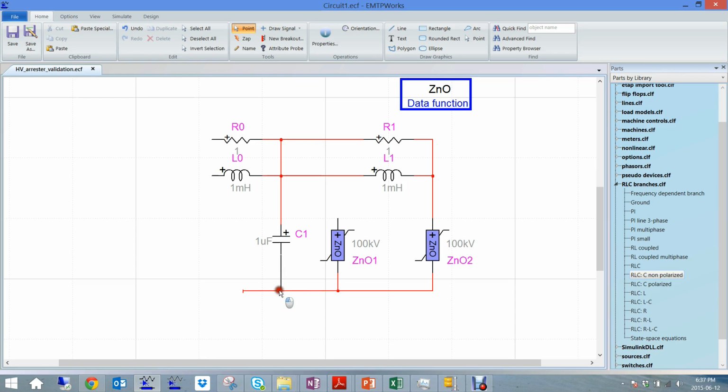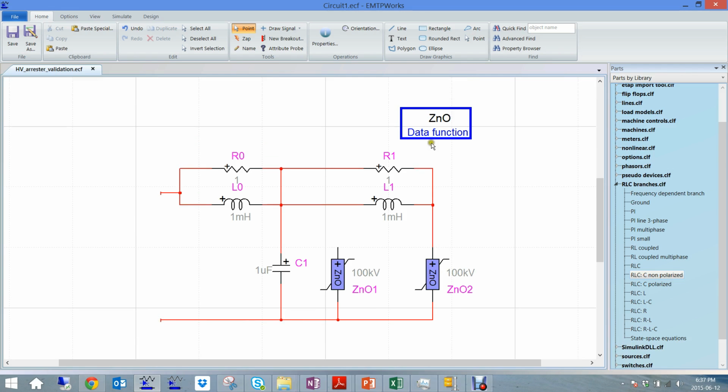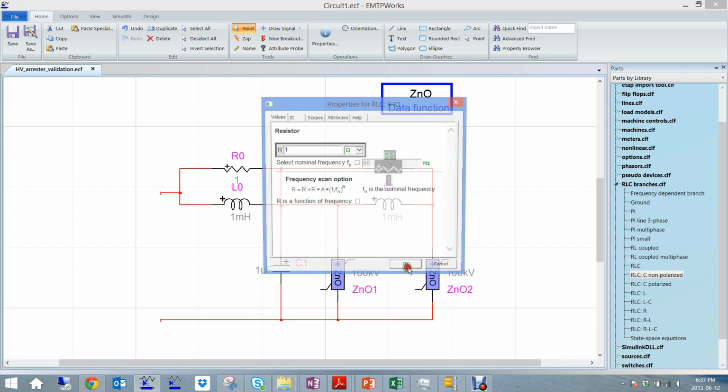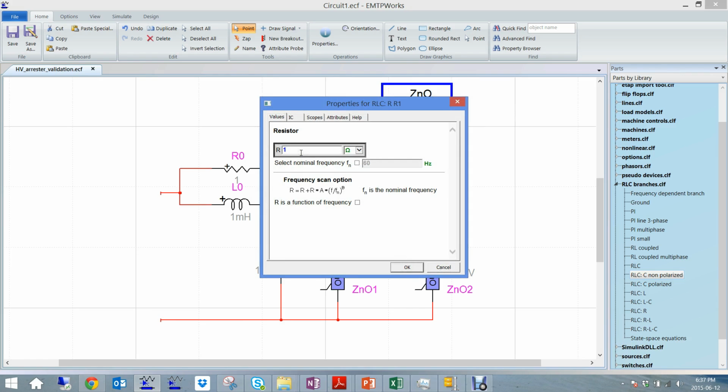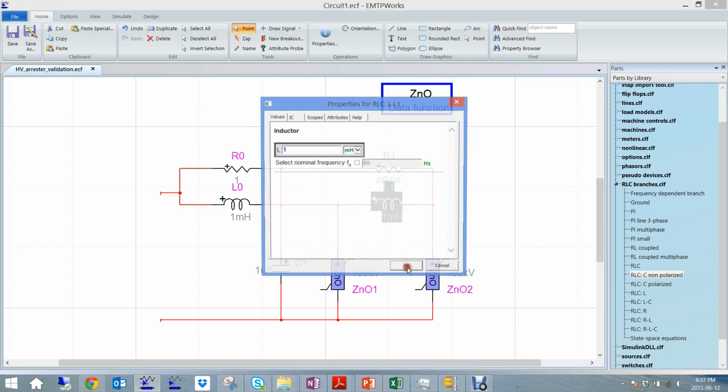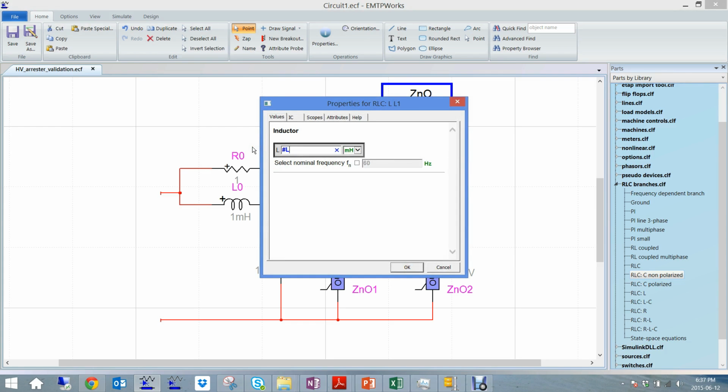So actually what I'm going to do is put all this model in a subcircuit, so that after it will be nicer to integrate in the design, and also all the parameters R0, L0, etc., I'm going to enter them in the subcircuit. So in the end, the variables will be defined in the mask. To do that, I just have to enter the parameters here between hashtags, and then I just have to define those parameters in the mask. I'm going to create the mask right after.